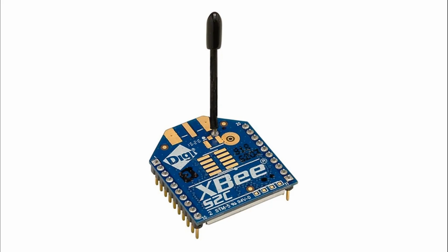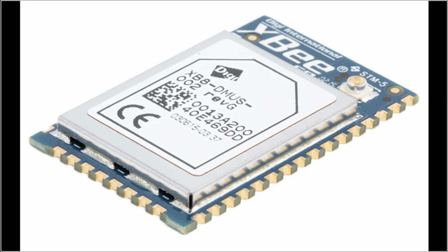3. Scalability. Zigbee networks can support up to 65,000 devices, making it highly scalable for applications like smart cities and industrial automation where numerous sensors and devices are needed. 4. Low data rate for efficiency. Zigbee operates at a data rate of up to 250 kbps, which is sufficient for applications that only require intermittent, low-bandwidth communication, like sensor readings. The low data rate contributes to lower power consumption, further extending battery life.